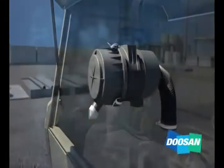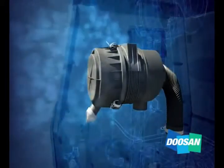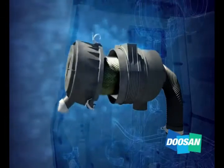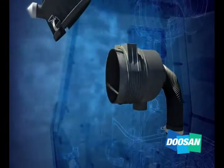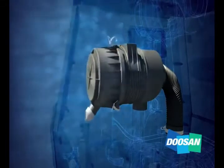Ambient air enters a compressor through a filtered intake which removes dust and dirt. This filter should be replaced at timely intervals to ensure the compressor is protected from unwanted contaminants. Dirty or restricted filters cause pressure drops and reduced efficiency.